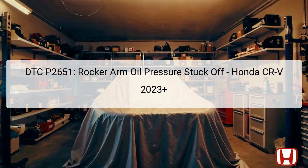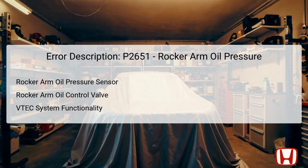In summary, when encountering DTC P2651, a comprehensive understanding of these components, along with their functions in controlling engine performance, is vital for effective troubleshooting. In the Honda CR-V, the rocker arm oil pressure sensor measures the oil pressure used to control the rocker arms. This sensor is located on the rocker arm oil control valve, situated near the engine's valve cover.